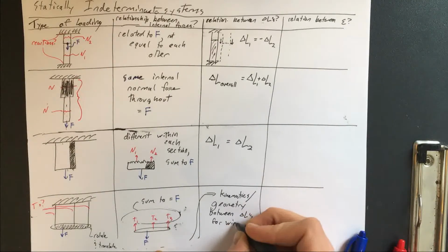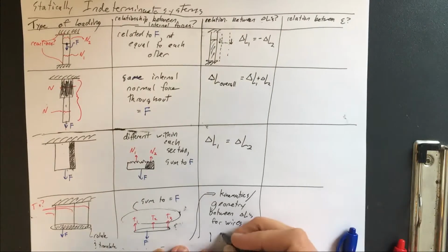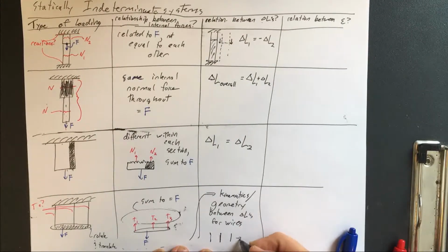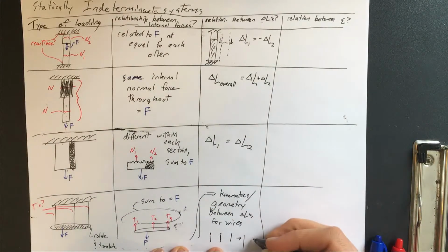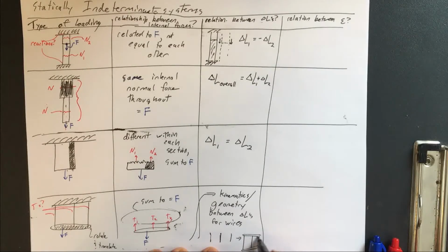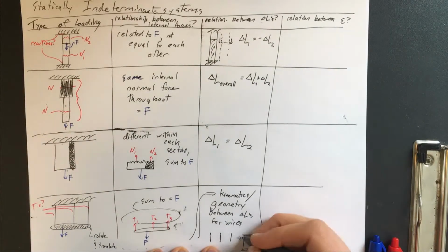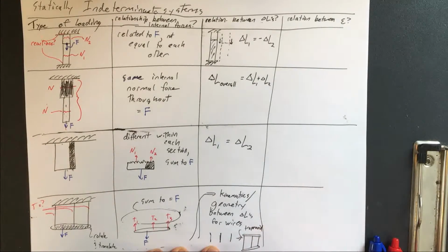for the wires. Right, so maybe originally they're all the same length, but then when they deform, the first one becomes longer, the second one becomes a little bit longer, and the third one becomes maybe least long if it's stretched in this way. So due to the geometry, this forms a trapezoid, and we can geometrically relate each of the increases in lengths.